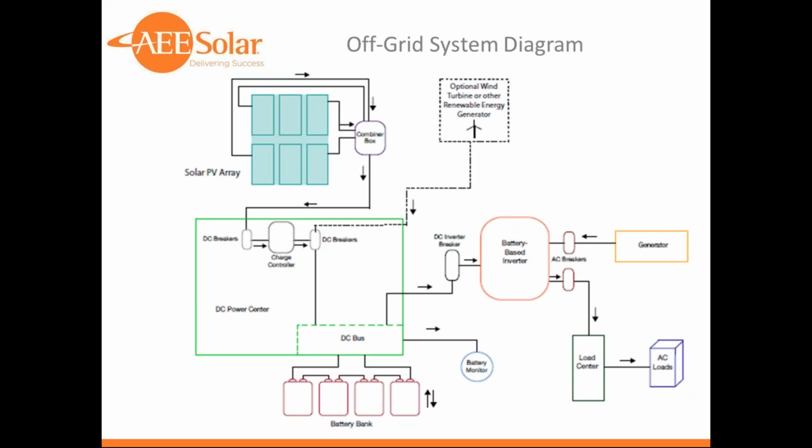Most of these systems are negatively grounded, so the overcurrent protection is in the positive lines. There are very few positive grounded systems. Some mountaintop telecom communications gear is positively grounded, but for most homes we have negative ground systems, so all the overcurrent devices are in the positive terminals.